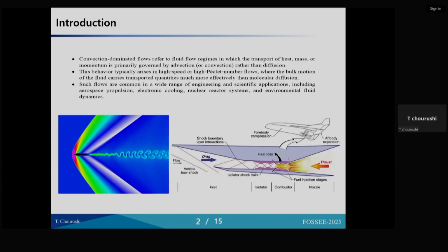The numerical schemes that we often look for are convective schemes, or convection dominated flow schemes. The reason is that when we solve any numerical problem in a control volume, the fluid properties flow very fast relative to the time constraint you set for your computational domain, and that is what we set with the CFL number. If the fluid has very high speed and I'm using a lower order scheme,